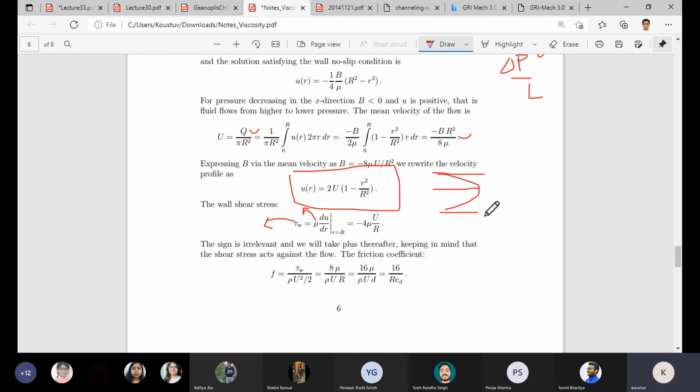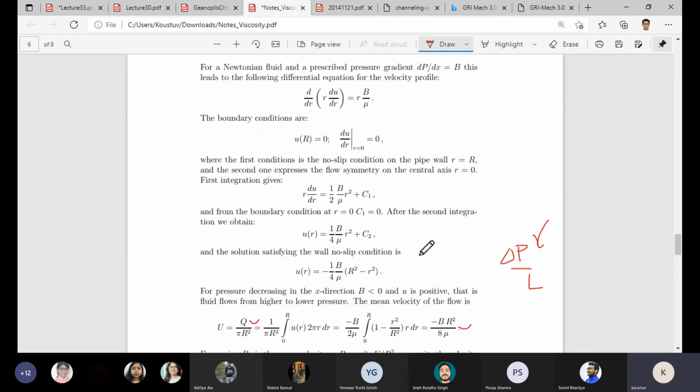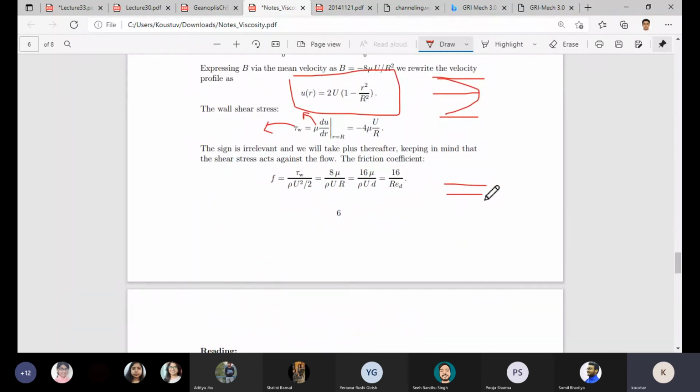For that we have taken different diameters of tube, one larger, the other smaller. So 4 different diameters, just to make sure the results get validated, and a larger sample size or number of operations would give you better control or idea of mu of water. Typically mu of water is 1 centipoise. So from that data, we try to see how much mu of water comes out. Of course the experimental results are associated with some kind of error.